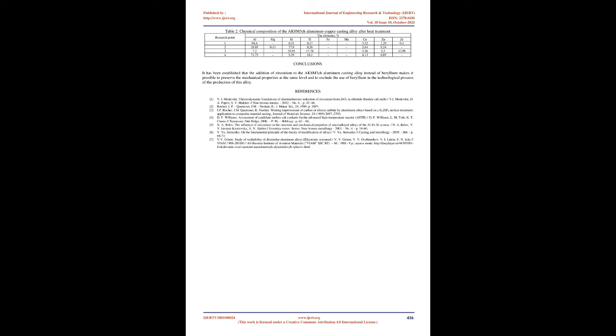It should also be noted that the brighter color of the structural component corresponds to the heavier metal that forms it. After heat treatment T7, the silicon content in the solution is significantly reduced. The number of areas of the solution increases, and its composition changes. Namely, we actually observe a solution of copper and zinc in aluminum. The network-like phase Mg2Si, 63.2% Mg, 36.8% Si, which was present in the cast alloy, is absent.